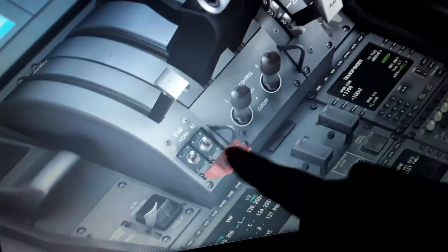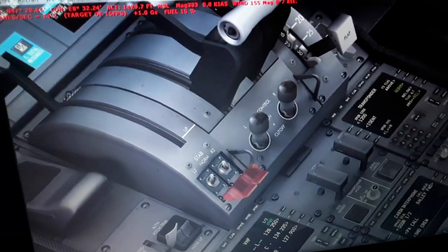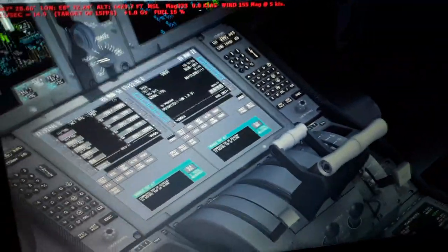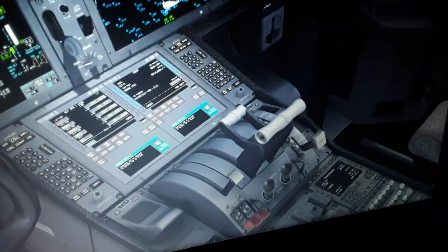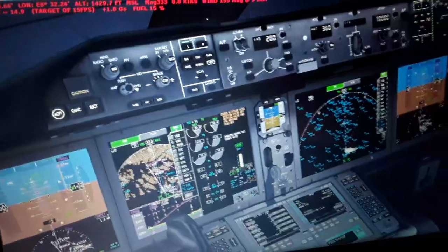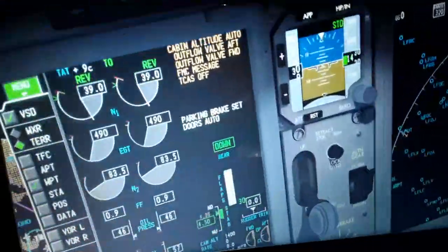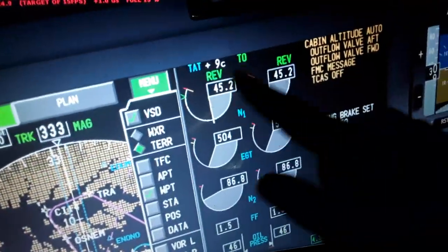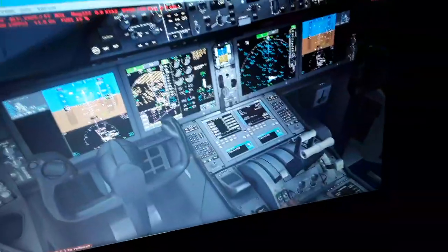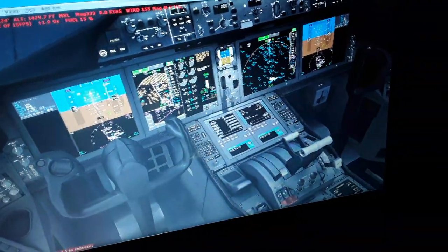So we have also, as I told, horizontal trim, speed brakes like this, extend and retract, extend like this, this position. We have the thrust reverse here. So we move this up, it will display the thrust reverse is being deployed right now. So you see with the green the reverse, and the thrust from the engines increases. So we disarm the thrust reverse like this.